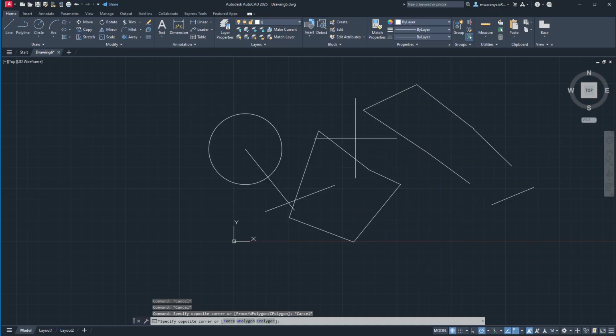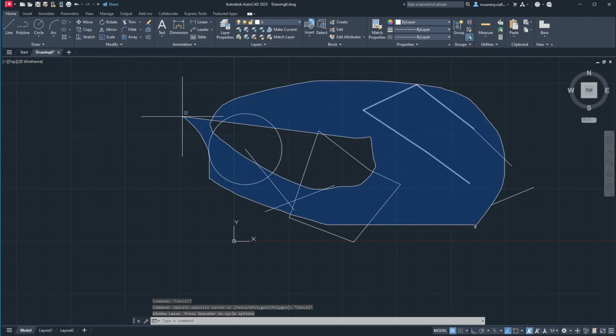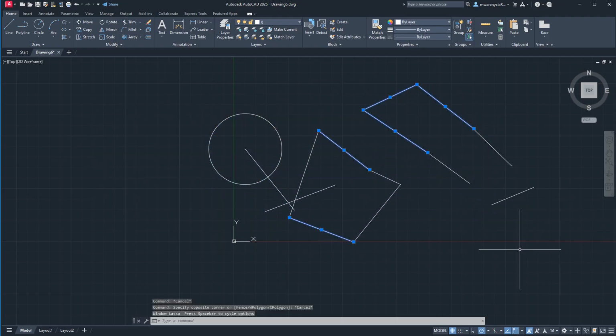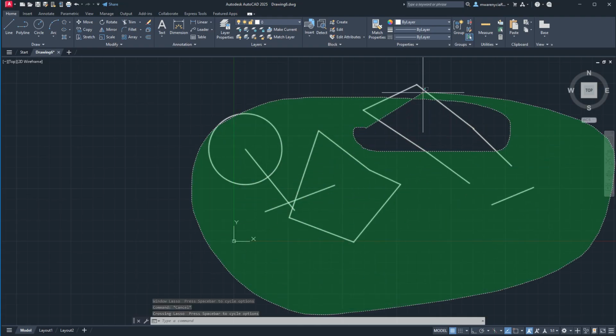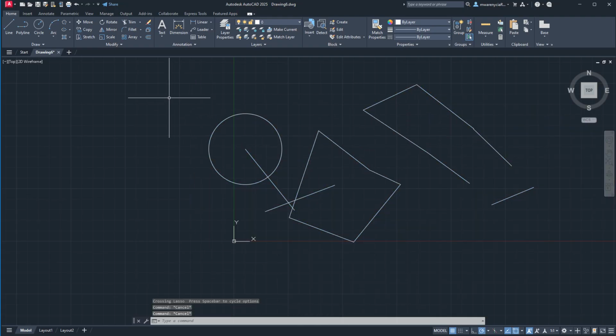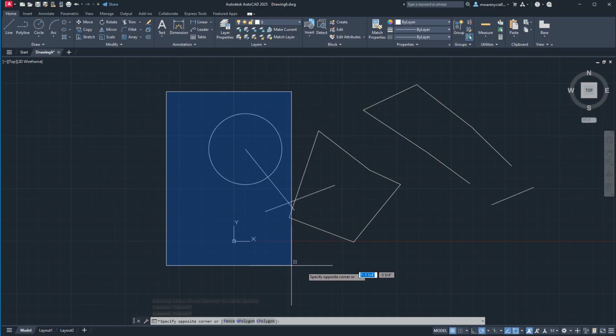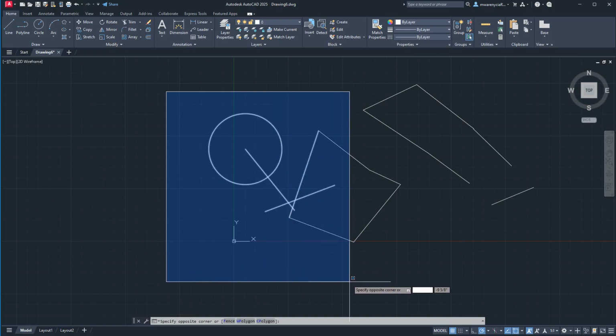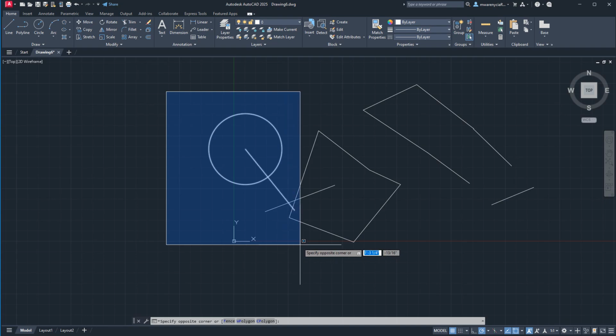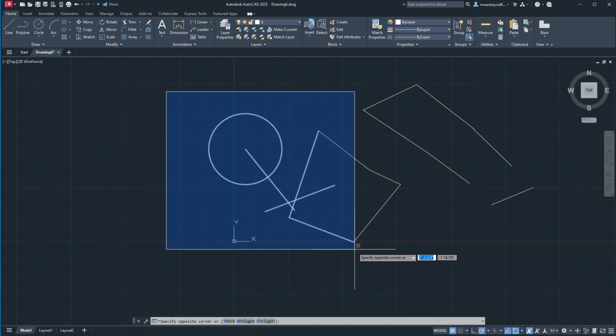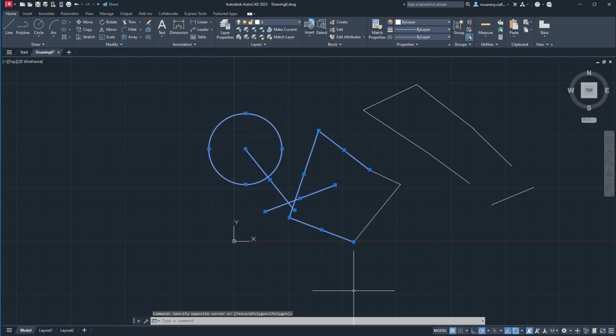It depends on which direction you're doing the click and drag. If I go off just a tiny bit to the right, it locks me into the blue mode, even if I go way out in a different direction. Similarly, if I go out to the left, it locks me into this mode. The blue selection grabs anything you fully go over. You can see as I move across, certain things highlight, indicating that they would get added to that selection.